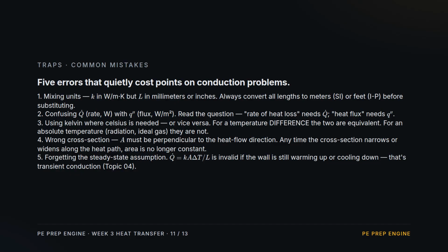Equivalent for a difference, not for an absolute temperature. 4. Wrong cross-section. Area must be perpendicular to heat flow. 5. Forgetting steady state. The plane wall formula fails while the wall is still warming or cooling. That's transient conduction. Topic 4.